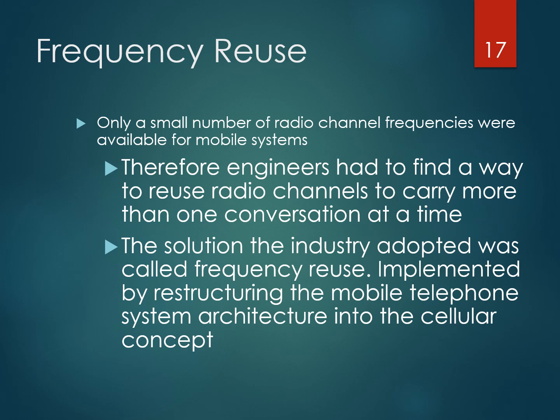So now let us see how frequency reuse is possible. Only a small number of radio channel frequencies were available for mobile systems. As I said, radio frequency limitation, for mobile communication it is 850 megahertz to tens of gigahertz. Throughout the world, it has to share the same frequency band. So the frequency reuse concept is a must. And let us see at what distance we can reuse the concept. For example, the frequency utilized in India, in a particular region, the same can be utilized in Gujarat or US.